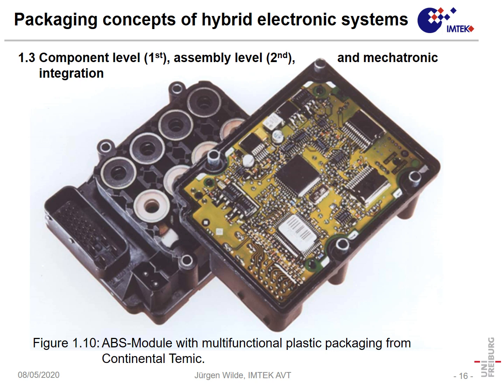Assembly and packaging comprises more. That's a so-called anti-brake locking system, and I don't know if all of you know how it works. Everybody knows what it is for. If you have a wheel in a car and that wheel blocks, especially if it's a front wheel, you can no longer steer the car, but it slides into the direction which you initially had.